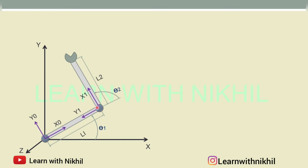Now you should keep in mind that this z axis and this z axis are parallel to each other. So the joint offset is 0, as here also the joint offset is 0, here also the joint offset is 0. It is rotated along the z axis, and for the link length, the x should be in line with the link. So here also the x should be in line with the link, and here also this x should be in line with the link. So now we have to find the DH parameters for this robot.